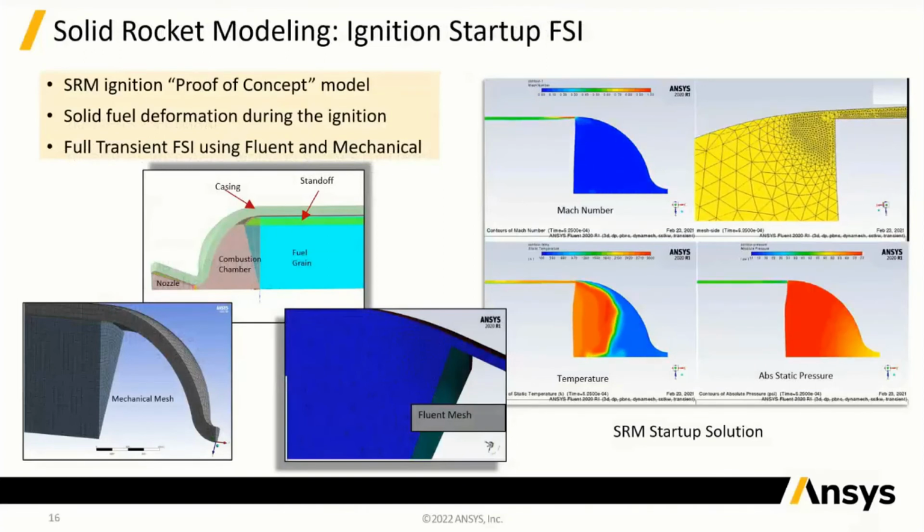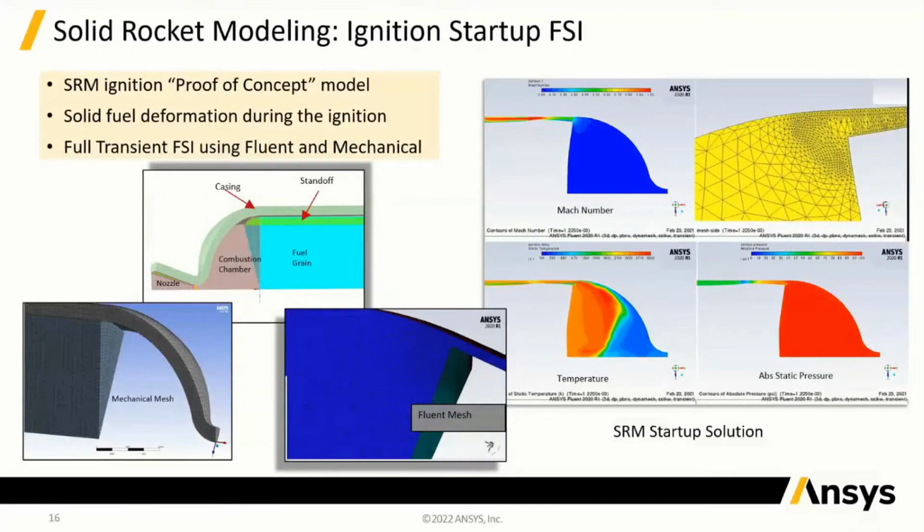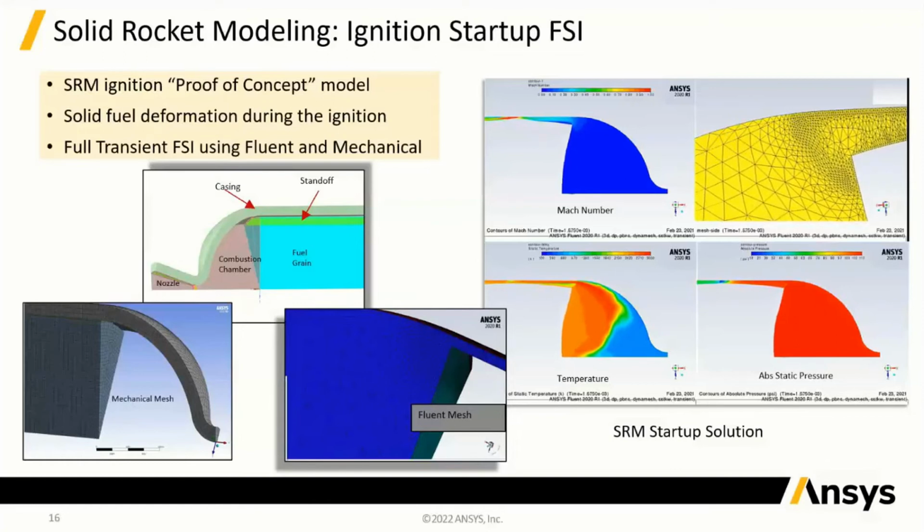Another part of the ablations is, this kind of shows from a rocket point of view, but it was a major issue with one of our customers: how to model the ablation and the startup process in the SRM. But they have no way of testing for this, so we were setting up some proof of concept models with FSI to be able to model both the solid fuel, the casing, and the gap to see if we can simulate what was going on during the startup process.